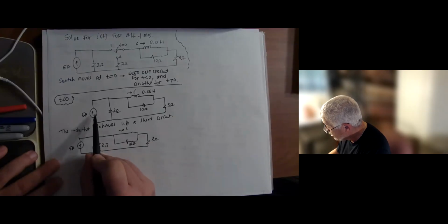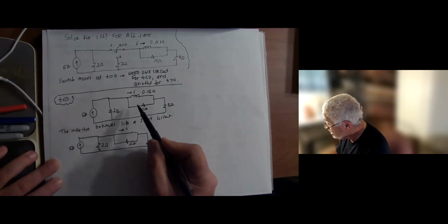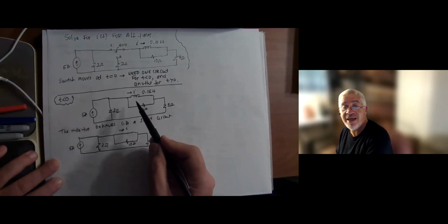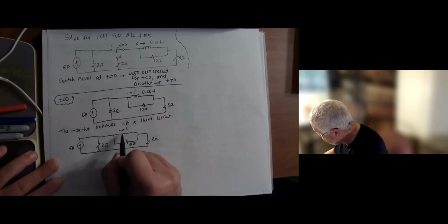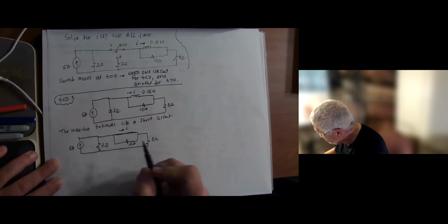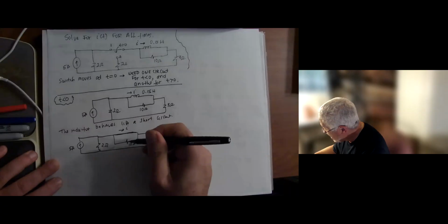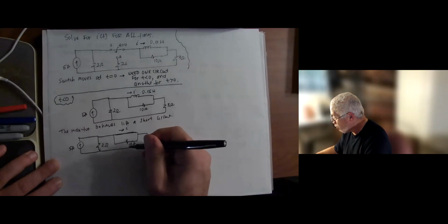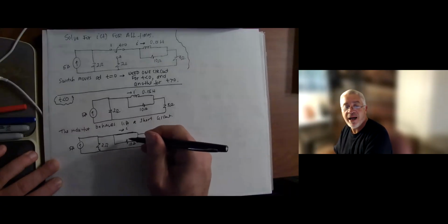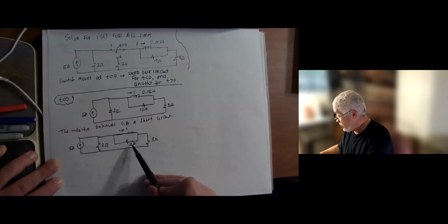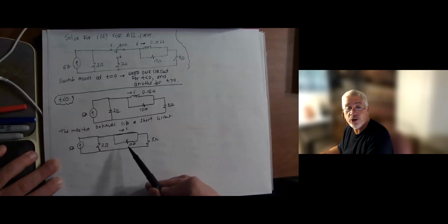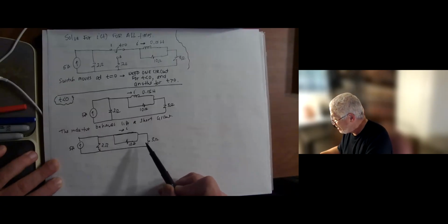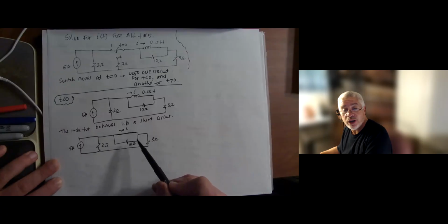we have a constant source. So the inductor sees no change in anything, so it behaves like just a straight wire. So that's how the inductor behaves. All right, so you can recognize that the inductor short circuits the 10 ohm. What I mean by short circuit is it forces the voltage across the 10 ohm to be 0 because it's just a wire. So the 10 ohm essentially has no impact in this particular circuit.